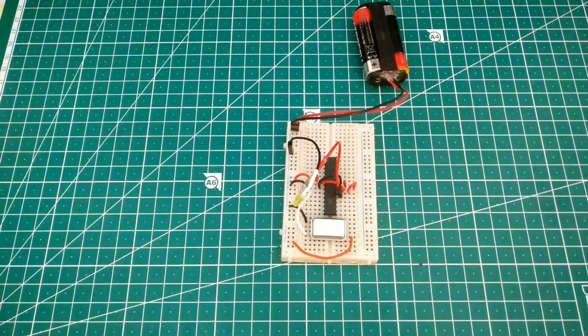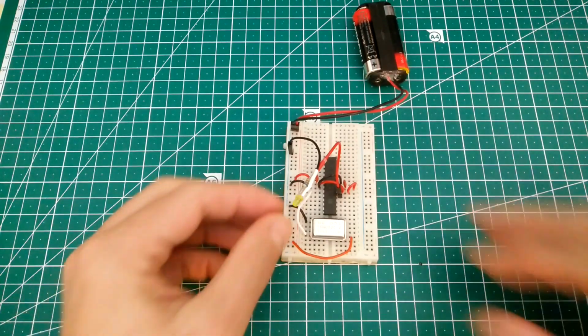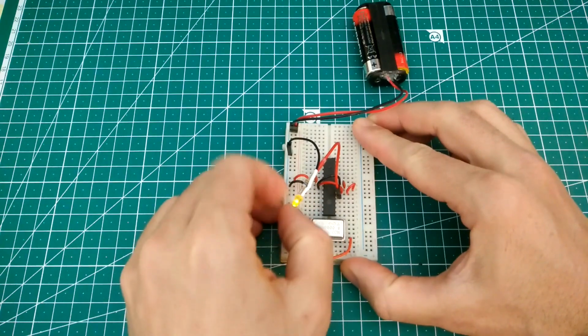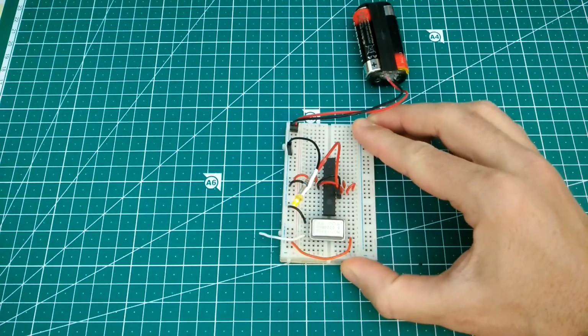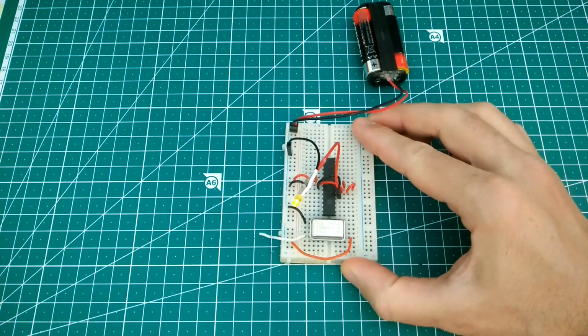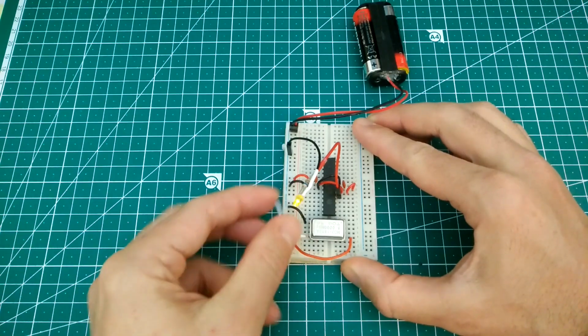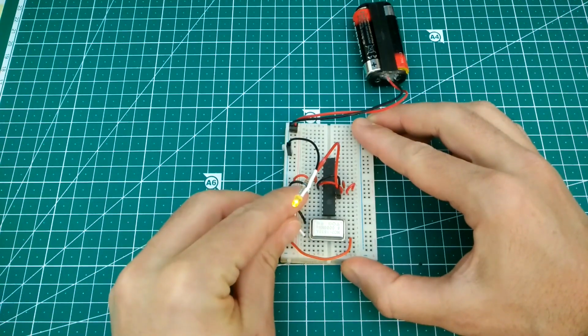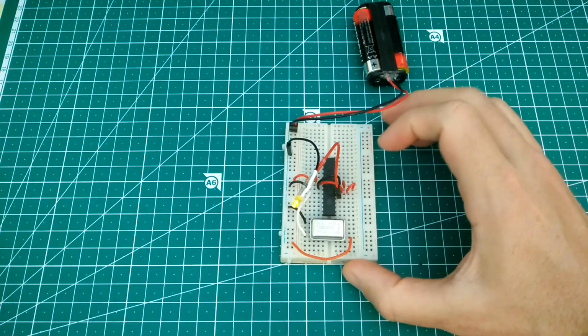I'm going to show you that this is in fact working by doing something quite simple. I'm just going to take it off, right? There you go. No clock signal. And you can see it's actually stopped mid-blink. The microcontroller is not being clocked. It's just not getting any up and down square wave cycles. So it doesn't do anything. It's completely frozen now. And restore it by wiring it back to the same pin.